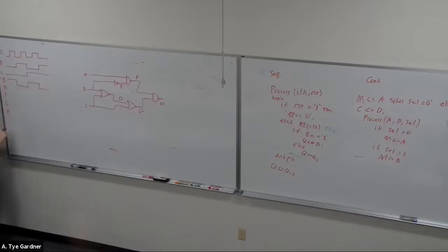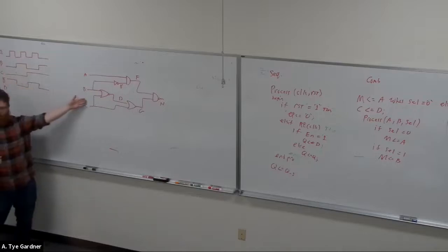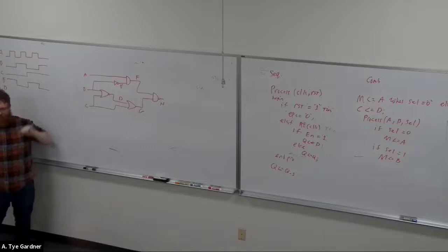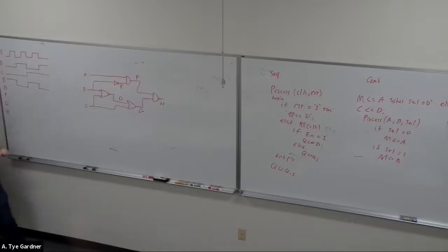And I will usually provide dashed lines vertically. Sometimes I forget this, right, to kind of help you mark it. If I don't provide them, draw them. Anywhere something changes is an interesting point if it's combinational. If it's sequential, the only interesting points are the rising or falling edge, whichever we're looking at in the code, right? So B naught is just the inverse of B.